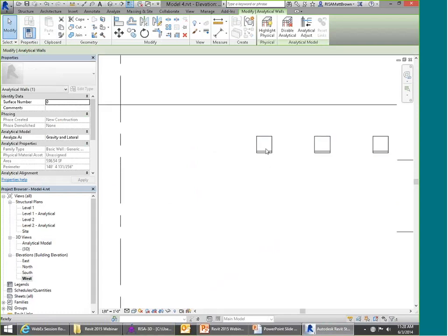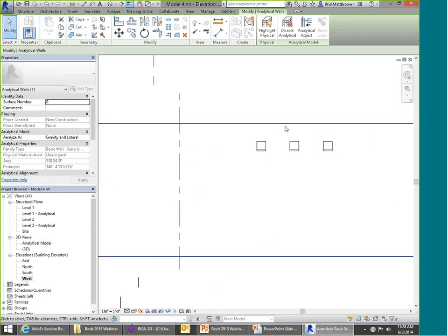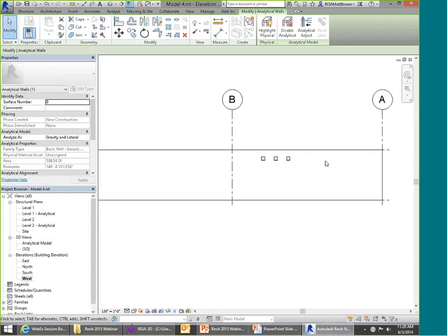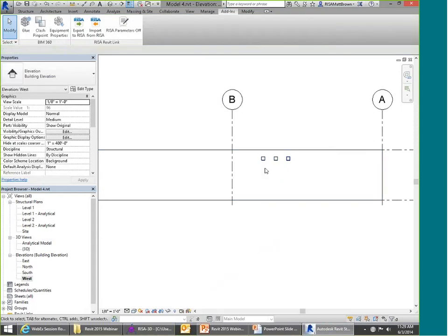In fact, these openings are only about 1 foot by 1 foot, and these openings were put into the model to represent piping penetration. Now, you may have this a lot in your Revit models because, of course, the MEP aspects of the model are going to have to run pipes through walls. And for the most part, you're not going to care whether there's a little 6-inch opening cut through the wall to have these pipes in there.